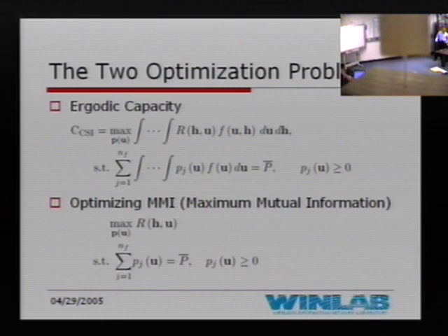So your problem in the second case is over frequency and the other one is over time. This is both over frequency and time, whereas here it's just over frequency. Given particular channel states in these frequencies and this total power, how do I put them in the different subcarriers? But your each channel corresponds to what? At any given block, I have this vector H1 to H of N. But is that over time and frequency? It's not about time and frequency.